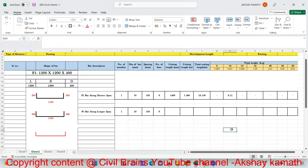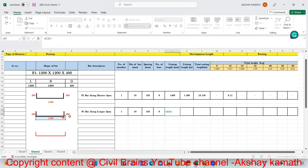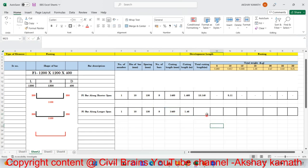Got it, no? Fine. Again, coming to the total cutting length. How do you find the total cutting length? Open bracket. So this 1100 plus 200 plus 200, close the bracket. Okay. So in this, you have to do the bend deduction minus open bracket 4 times the D. So 4 multiplied by D. Diameter is 10 here, right? And close the bracket and hit the enter button. Finish. Again, it is 1460, obviously. And this will be, again, open bracket 1460. You divide it by 1000 and close the bracket. Finish. 1.46.